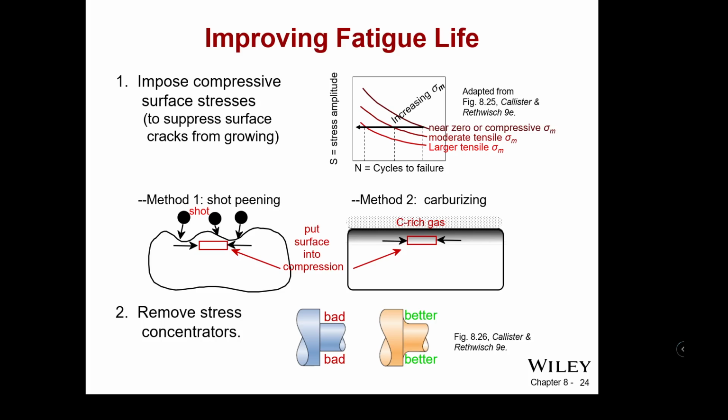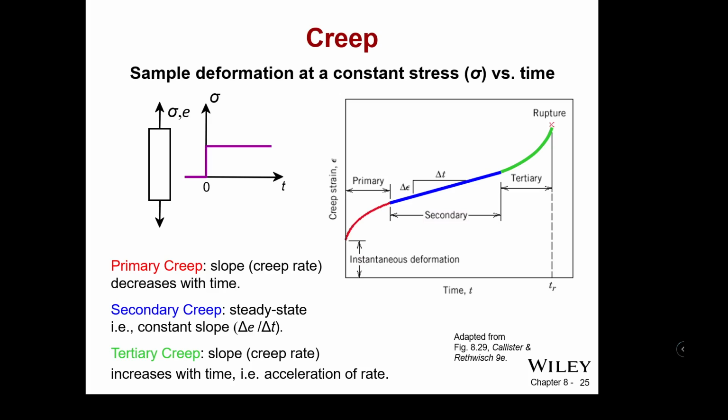You can then improve your design by reducing the stress concentrators by adding radii where sharp corners are, so that you don't have a single step from a lower stress to an immediate higher stress, creating a designed failure point right at the transition. So the reason we do fillets and things in the drawing stages is we know that sharp corners tend to concentrate stress and create points where our stuff is going to want to fail.